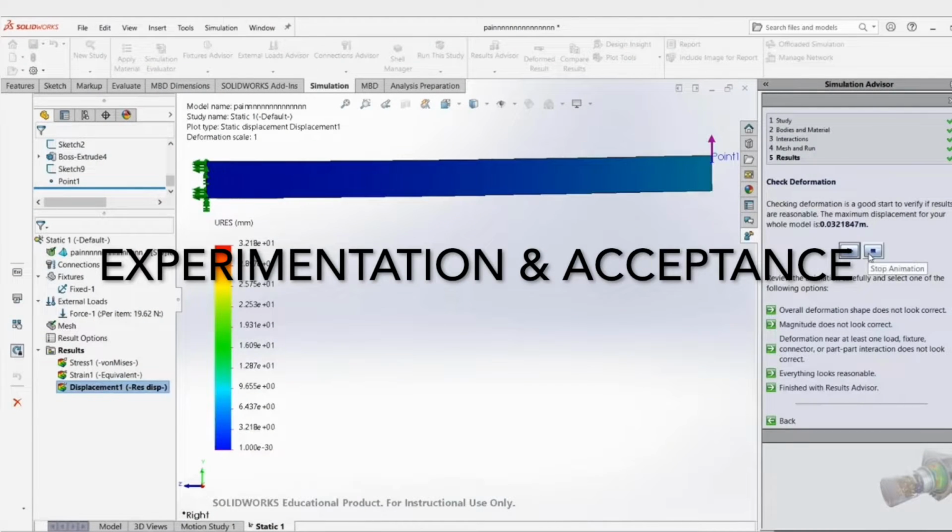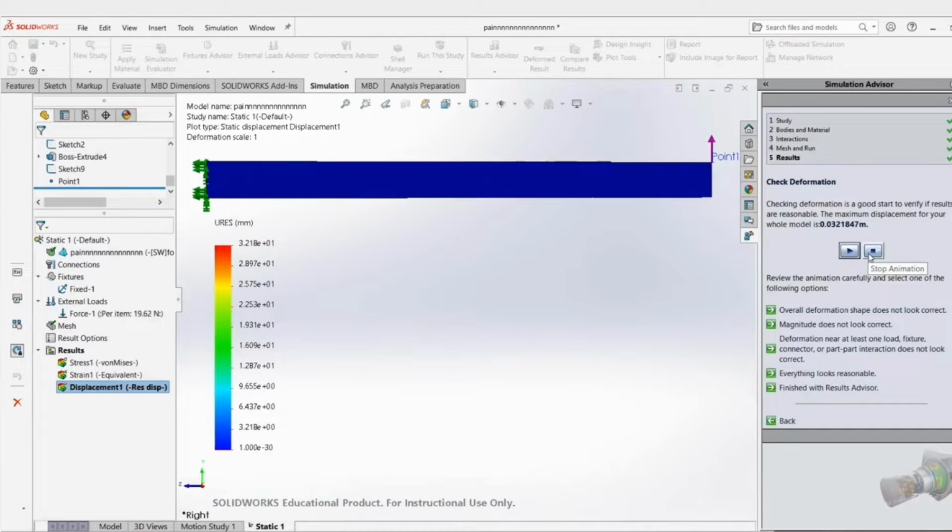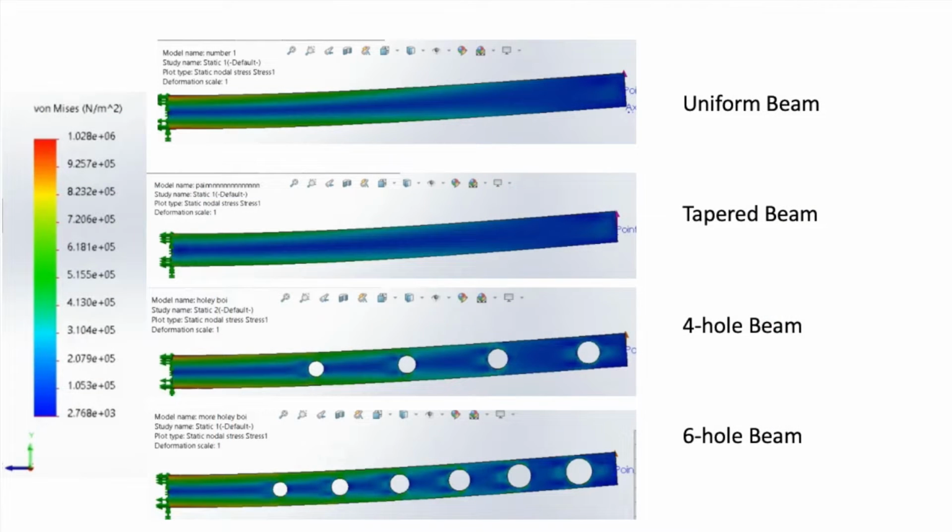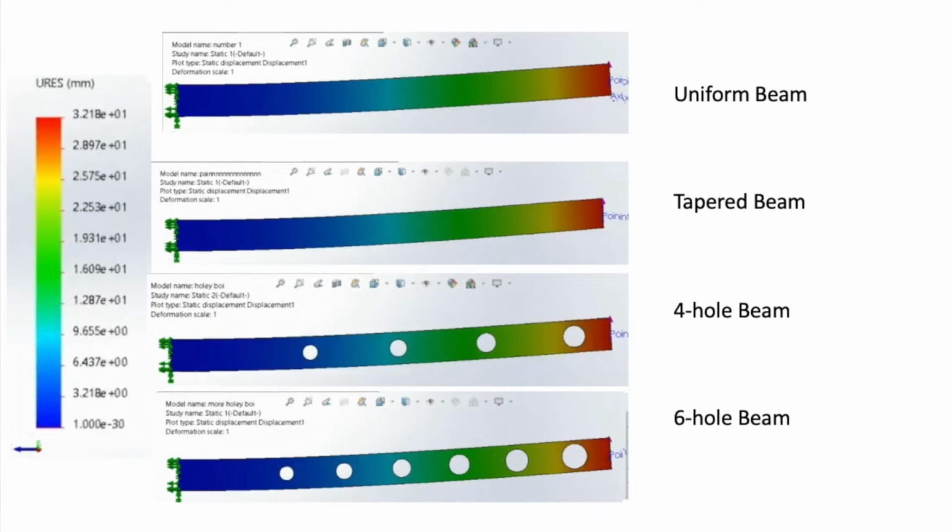Using the simulation tool in SolidWorks, we could demonstrate further how the tip experiences the least stress due to the maximum bending moment at the root. Using this simulation, we tested our original rectangular spar, 2 spars with the same cross-section with holes cut out from the tip to reduce mass, as well as a tapered spar.